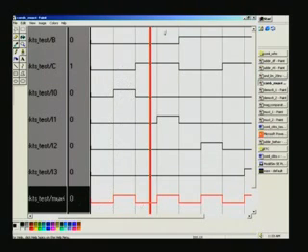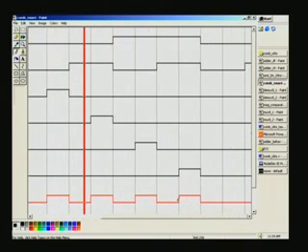And in the next, when BC changes to 0, 1, what you have is I1 appearing here. You can just see here. And mind you, it happens right at this stroke of change. C is changing here, and right at that point of time, it switches to the second input. So what you see right from here till the end is precisely the I1 signal. And so is the case for I2 here, which appears here, so you get the output corresponding to that. And finally for the last one, this is I3, corresponding to B and C being 1, 1. You can see this is 1 and this is 1.